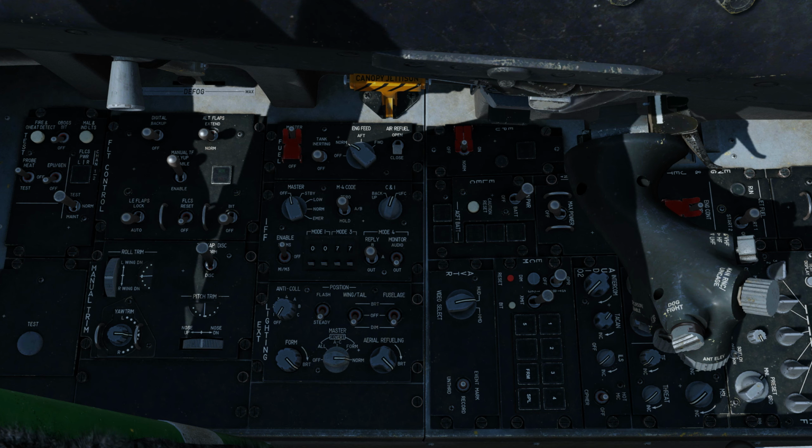The green EPU run light illuminates when the EPU turbine is within the proper range and EPU hydraulic pressure is above 2000 psi. The yellow air light illuminates when the EPU is running on bleed air. Engine RPM should be maintained between 82 and 90% to prevent use of hydrazine. The yellow hydrazine light illuminates when hydrazine is being used to boost bleed air.